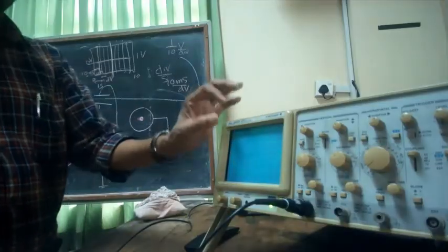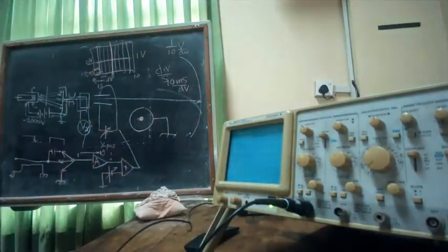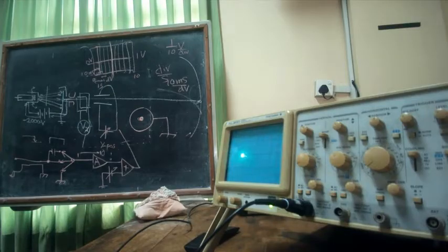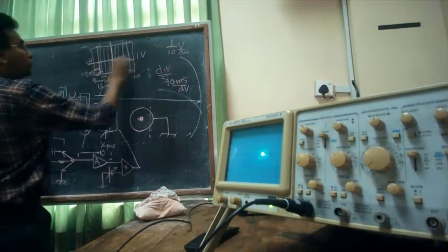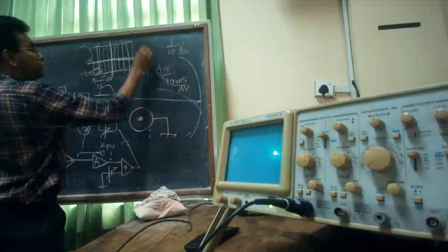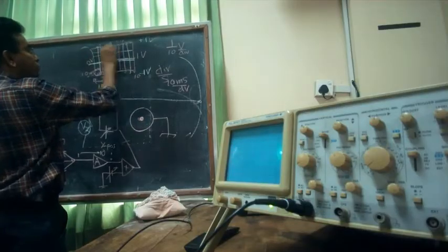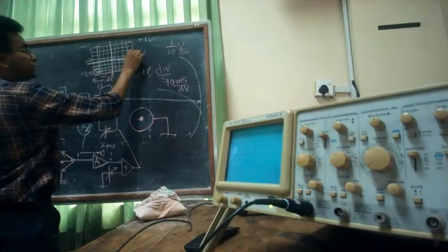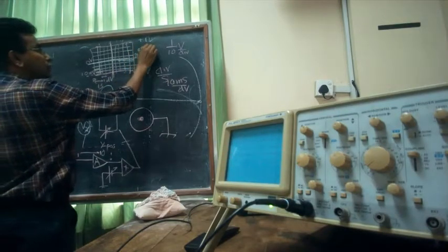Okay, some value, right? So this one division is 250 millivolts, just like the time per division one was 100 millivolts per division, right? So like this, here 250 millivolts per division. There are four divisions from center to the end, right? So that's why we took it like that. This is 0 for voltage, so y direction. This is minus 1 volts, this is plus 1 volts. So therefore there are 4 divisions. So one of these divisions is 250 millivolts.